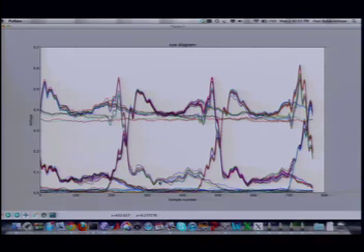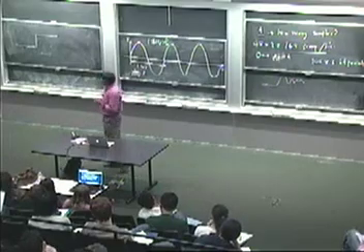From superposition, you would really expect to see the same shape on the downslope that you see on the upslope. So when you look at the upward transition here, you see a certain shape. It's not quite matched on the downward slope here. And the reason is that the particular simple demodulation that we're using here for this on-off scheme actually makes it not look very linear for channels that have this kind of an overshoot to them. But the other scheme that Harry mentioned, the quadrature demodulation, will actually do a lot better. We in fact saw that, right?